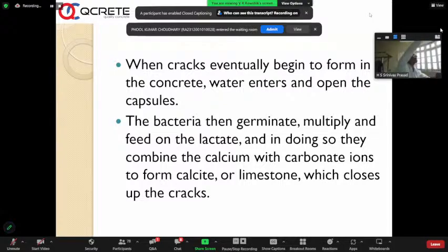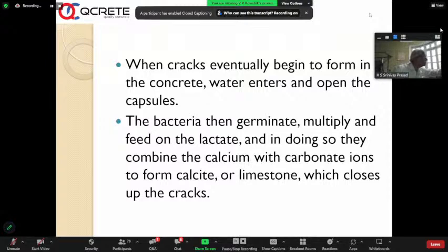I can say self-healing concrete has been tested in the Netherlands by Dr. Jonkers and one company in the Netherlands, and they have made pilot studies and have done all durability studies, including how it heals the cracks and things like that. And they have specified about 5 to 10 kgs per cubic meter of concrete.